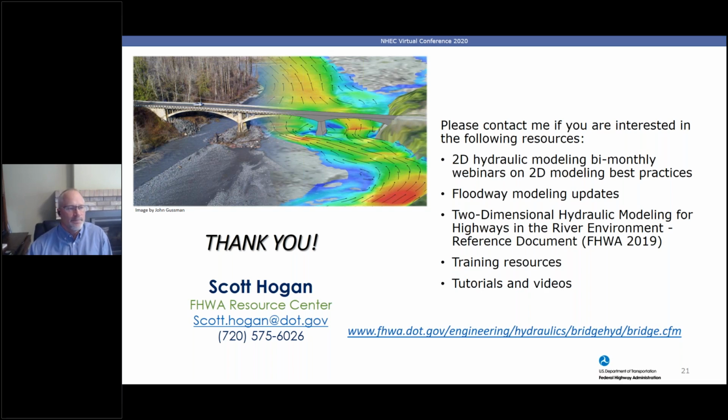Sounds good. Question: would it be better to use a straight line approximating the BFE contour as a better evaluation section? So would it be better to use a straight line? I would say no, based on what I talked about earlier. When we place that straight line, we don't know where that actual water surface elevation is constant. And bottom line, that straight line is not representing where the flow is necessarily perpendicular, or if the water surface is indeed constant along that line.